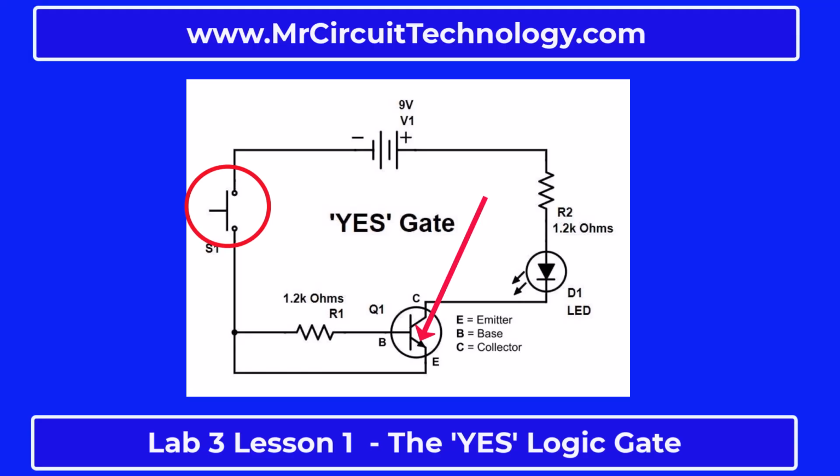When you press switch S1, the transistor is forward biased, and there are two paths which carry current through the transistor. One path is from the emitter through the base, and the other path is from the emitter through the collector. The current coming out of the collector pin goes through the LED, through resistor R2, to the positive of the battery, and lights up the LED. When the LED is lit up, it indicates a true, or a high, or a 1 on the output.